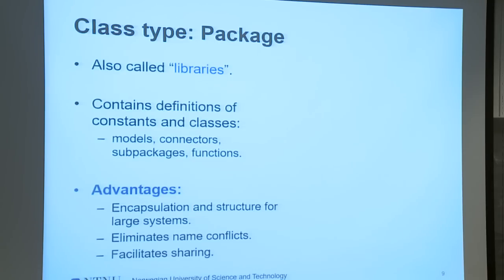The top package was Modelica. The first sub-package was media, the second sub-package valve, and there you have the valve sorted. That is one nice way. With packages, you eliminate name conflicts. It's kind of like in MATLAB, if you use structures for programming, the same applies for packages. You have always the name of the package, point, the name of the sub-package, point, and so on. So it's quite easy to name the same model or use the same variable multiple times. And with a package, it's just one file.